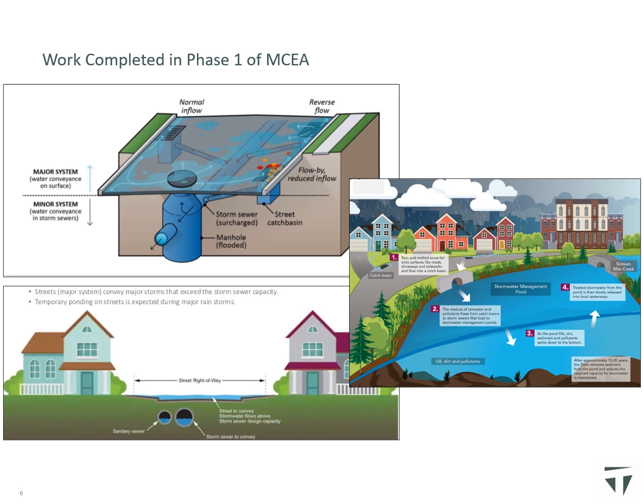In simple terms, the minor drainage system prevents nuisance flooding and provides public convenience while using roads during smaller, more frequent storms, while the major drainage system conveys flows and prevents flooding during significantly less frequent storms.